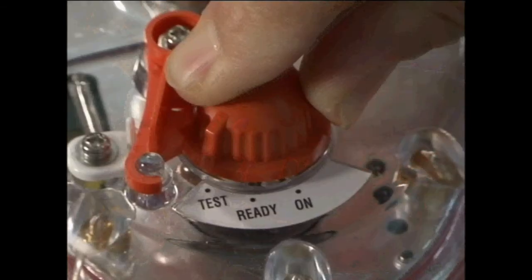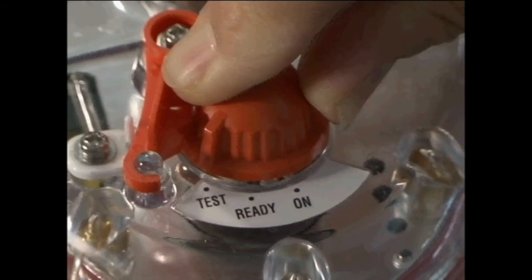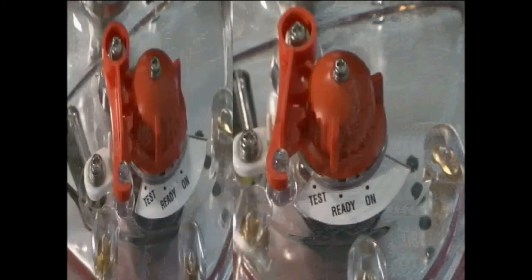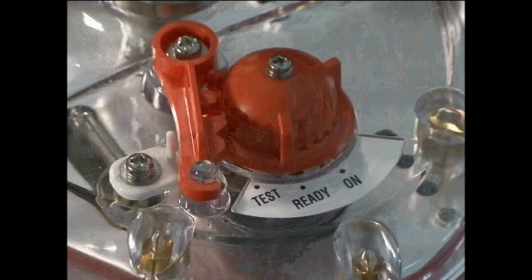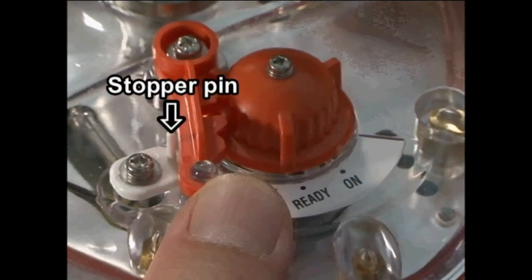Test mode is used to check EPIRB functions. It can be set without breaking the stopper pin. On mode is designed to activate the EPIRB and purposely transmit a distress signal. Break and remove the stopper pin to set the EPIRB to on mode.